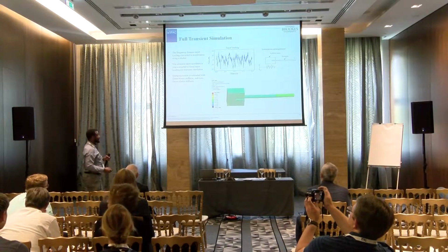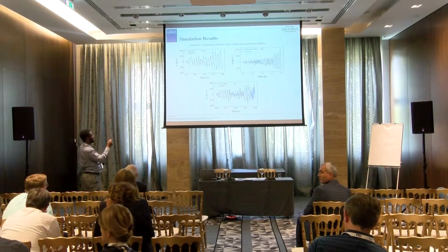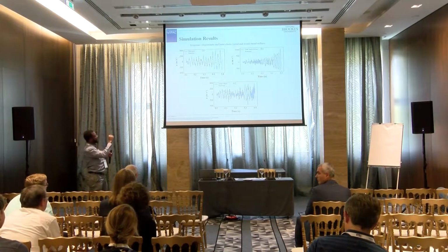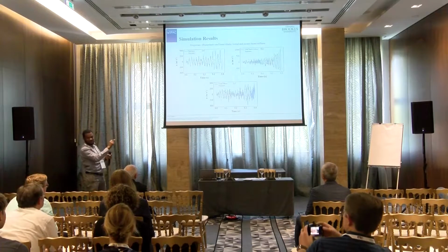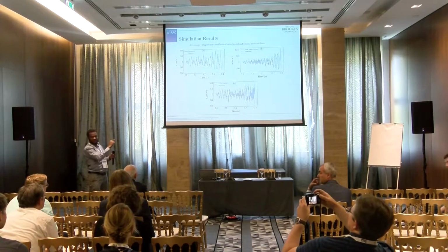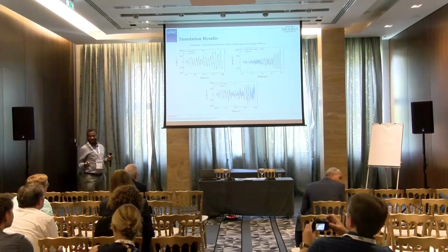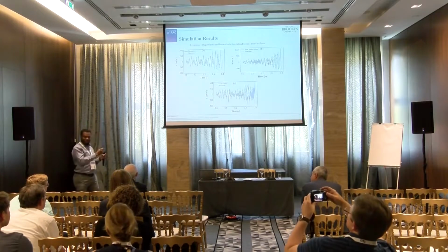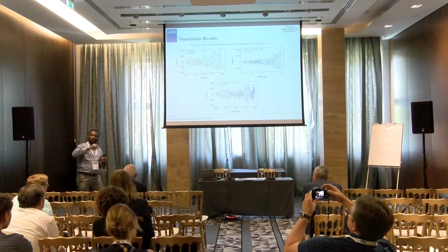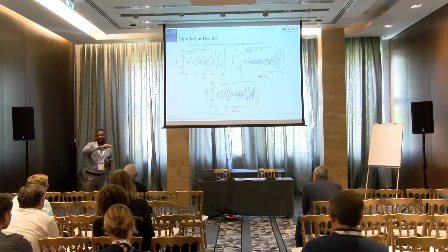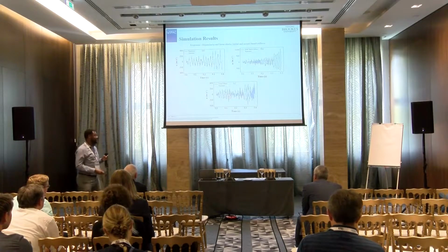Now, here we go. This is simulation results. For hyperelastic, we can see that the curve follows quite well with the experimental curve, compared to initial tensile stiffness and secant stiffness. So you have a good match for the hyperelastic model. Why is that? Because it's a non-linear model, so it's following the non-linearity. The elastic modulus is dropping as it should drop in real life, rather than having a constant value of tensile stress. So it's a good match.